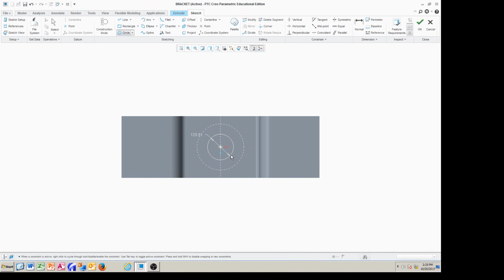It has to be concentric because it's going to cause problems when we do assembly. If it's offset and it doesn't match, when we add other features, other parts trying to fit in here, it will be offset and it doesn't work. So you make sure that that precision is important, okay?